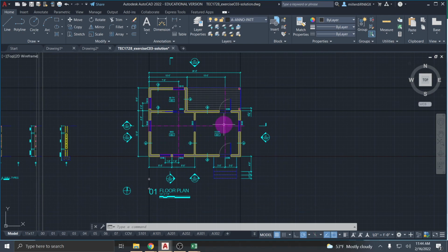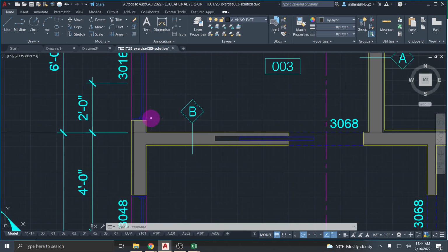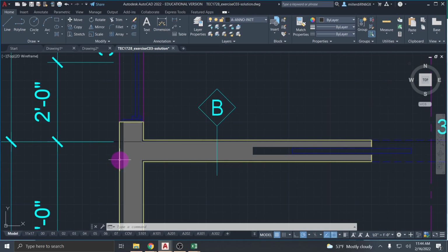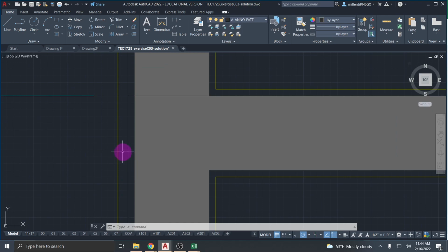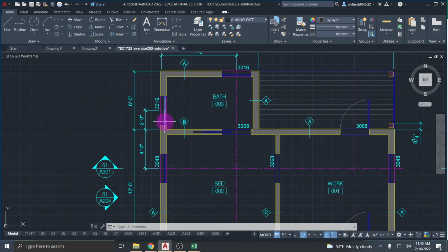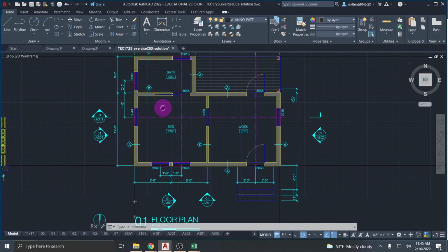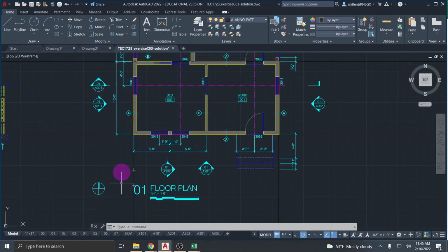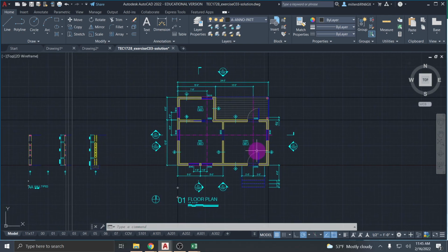So it's again, for those of you who are retaking, it's your hauntingly familiar building. And so I've got my floor plan here, and I've got these different colors designating just different areas. So like the very outline of my building versus then the layer to represent my siding. So from here to here is the outside of my siding versus my plywood sheathing versus my stud versus my gypsum wallboard. So it's just the different layers of the wall because the wall is made up of a composite of material. My different symbols in my drawings, my title, my graphic scale, all of my dimensions. Even on a small building like this, it's a lot of information to look at.